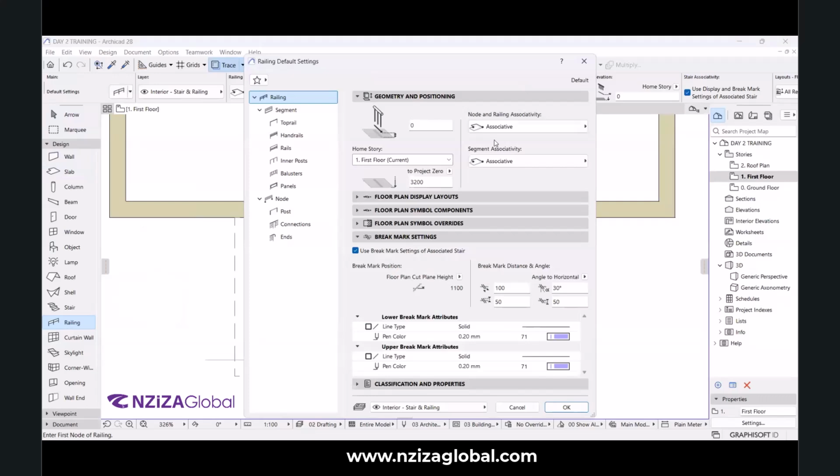Now, follow. Here there is the associate option. What is this? This is a way of placing railing. When it is associate, the railing you are going to place detects the structure where you need to place it. While when it's static, the railing goes horizontal. It doesn't follow anything, just the area and the height you set it on.